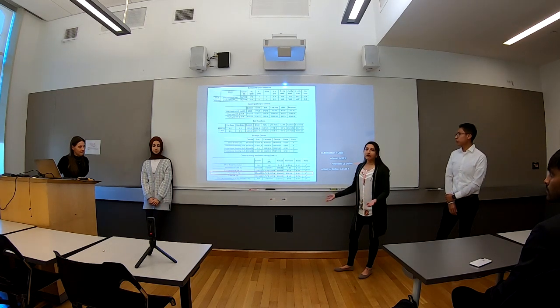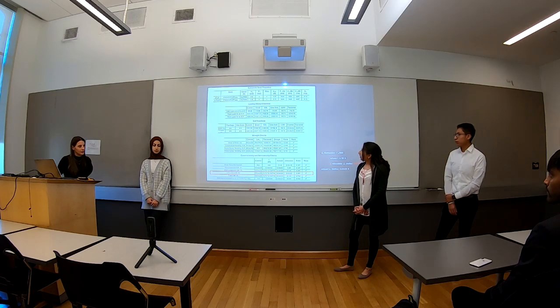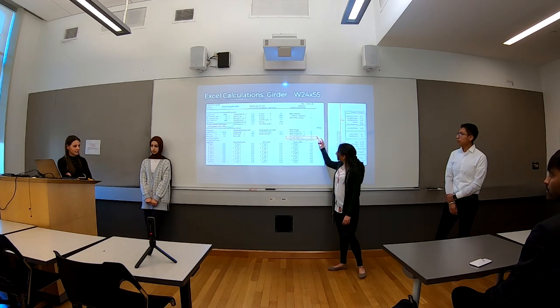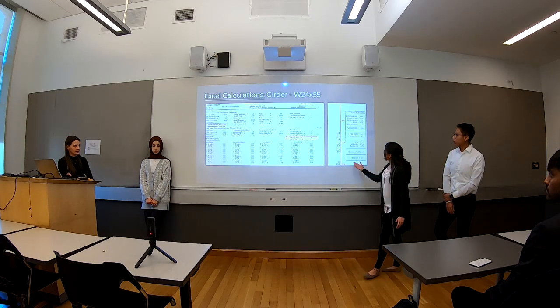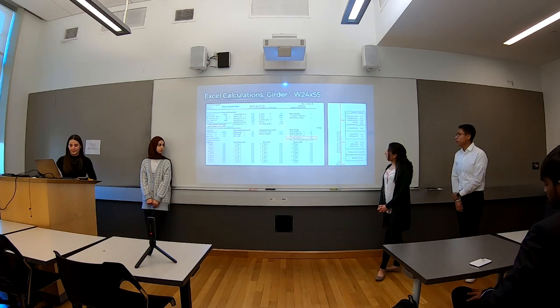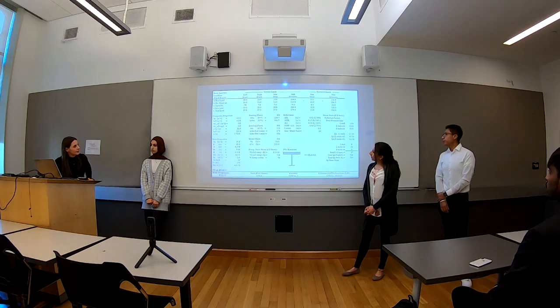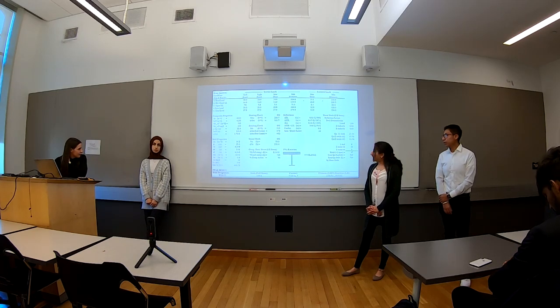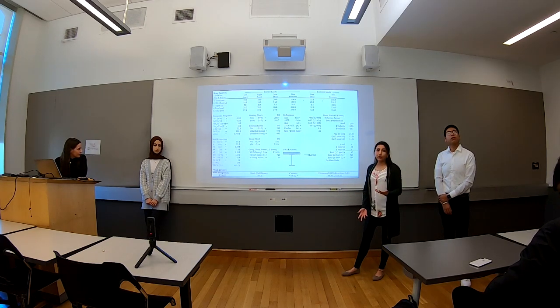And here again, we had the report telling us that everything works out and the design is adequate. He also ran the Excel calculations with composite action of 90% again with the beam section that we chose, and as you can see, the design was approved and the calculations ran through. As you can see, we found that this beam design works with our floor plan with studs, 94 studs required